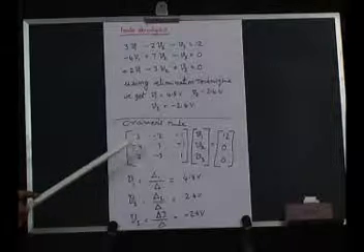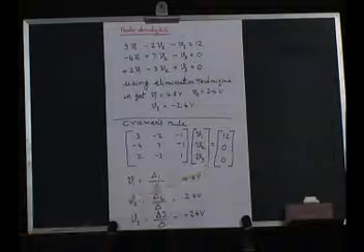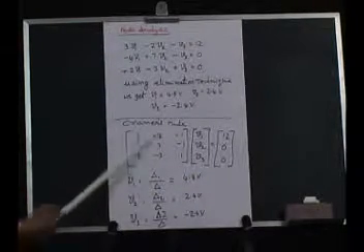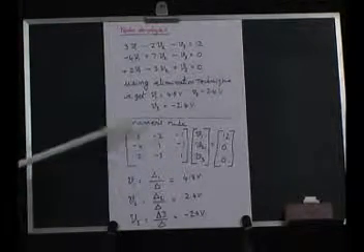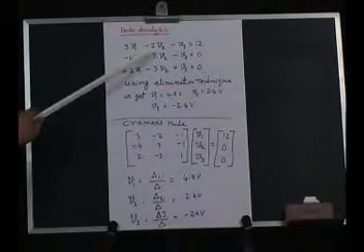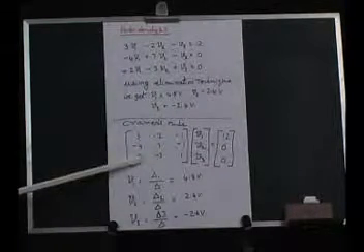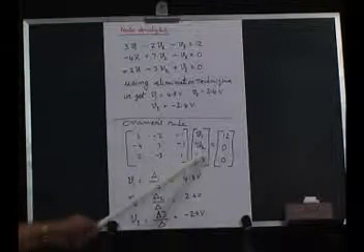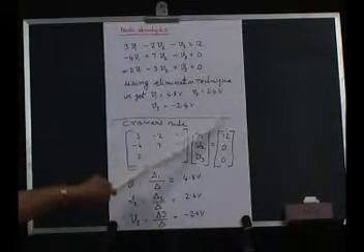The second method of solving the simultaneous equations is by Cramer's rule. Just now we have seen how it can be worked out. First of all, we put it in matrix form. The coefficients of V1, V2, V3 are put here. This is the coefficient matrix. If you look into the first row, this will be 3, minus 2 and minus 1. And this will be minus 4, 7 and minus 1. Likewise, you have 2, minus 3 and 1 for the third row. These are the values to be found, V1, V2 and V3, and this is the constant matrix 12, 0 and 0.